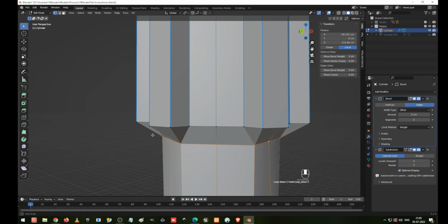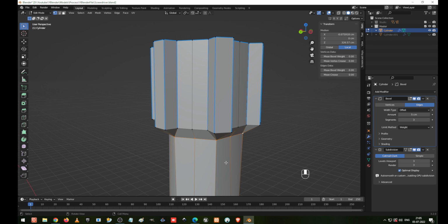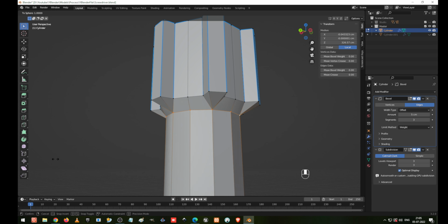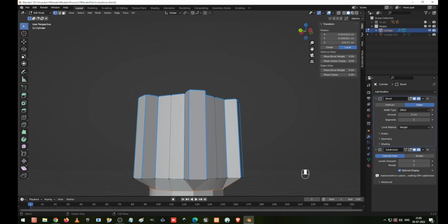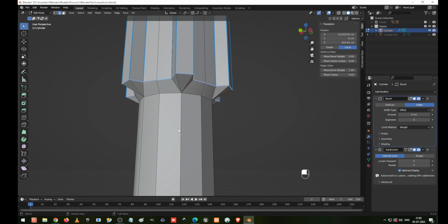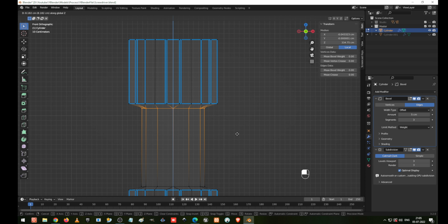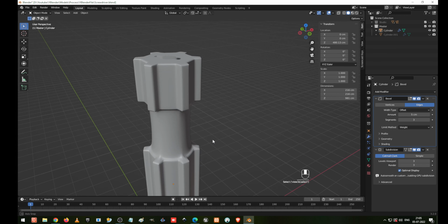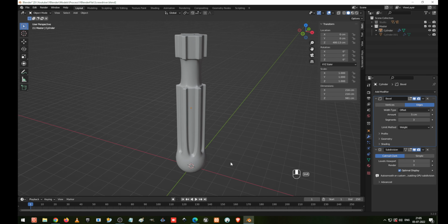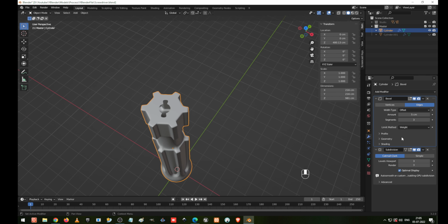Okay, after selecting everything, press Alt Shift S and make it a circle. Now we can view it better. And I go to the edge selection, I'm going to make a bevel 1 and go to the front view, go to the wireframe and vertices, G select and Z to move upwards. So now our bottom has been made ready. Okay, and we are going to give thickness to this.